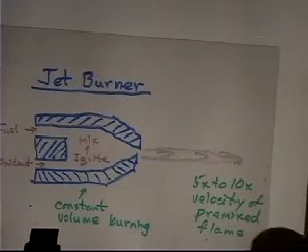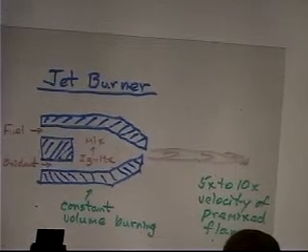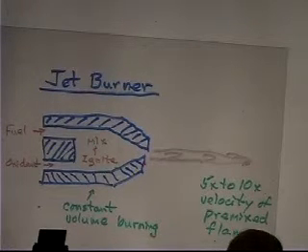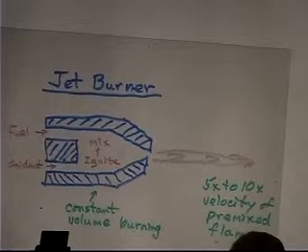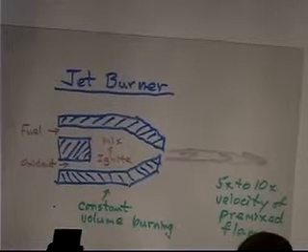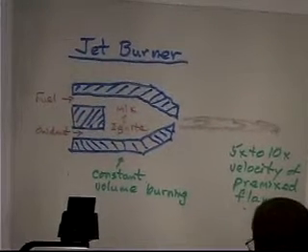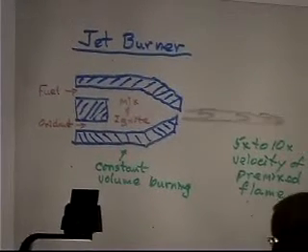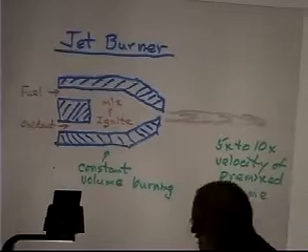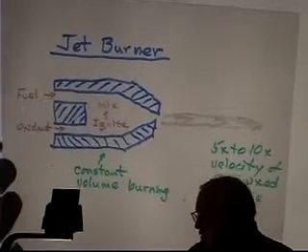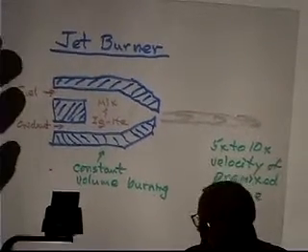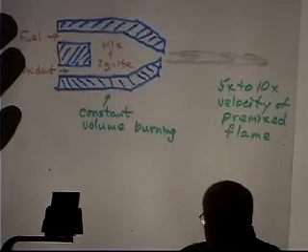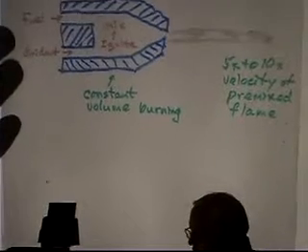So there are fairly wide ranges here depending on the actual velocity and the size of the flame and the type of gas and stuff. But the intensities of a diffuse flame, let's face it, if you had a house fire, the flames are not usually going to be more than about 10 watts per square centimeter. And that's plenty to give you a sunburn or burn you and whatnot. But it's not going to melt steel or copper very well. It won't melt either one of them because it doesn't get hot enough in air. But even aluminum, which it might get hot enough to melt, is going to take a while to do it. It's not going to melt in the first couple of minutes.